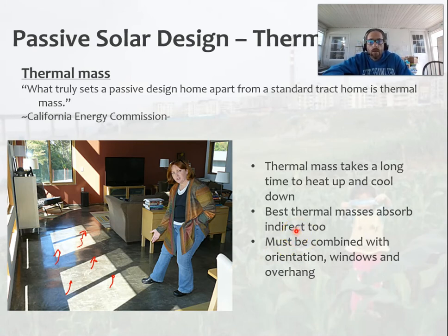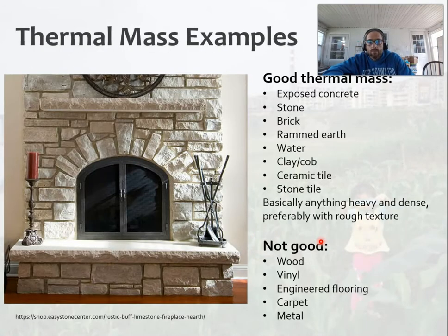Okay, and again, this needs to be used combined with orientation, windows and overhangs to really work. You need to have this in the sunlight in a south-facing wall with windows, right? And thermal mass, even though people don't use it a lot in green building per se, or in a normal building, it was really common for, I guess, well, hundreds of years at least. I don't know if it goes further than that.